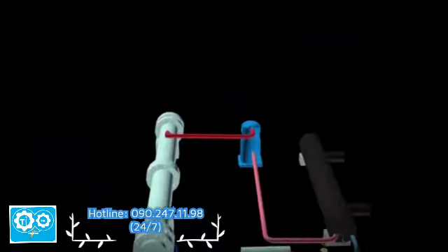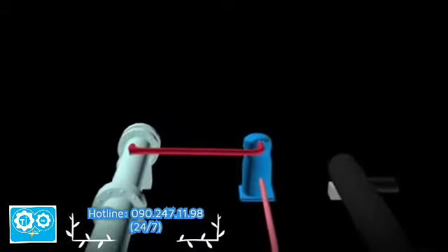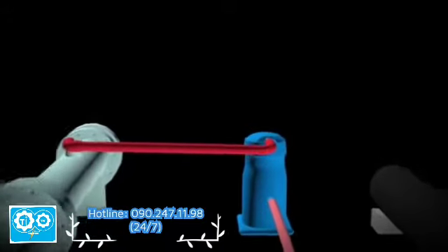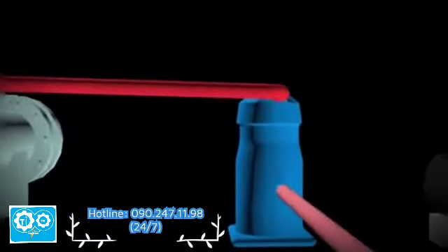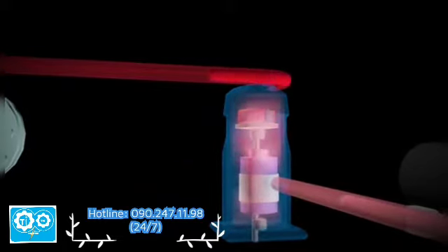Compressor. The compressor works to increase the pressure of the refrigerant. In addition, it also serves to increase the temperature of the refrigerant higher than the temperature of the condenser water so that heat transfer can occur in the condenser. The refrigerant enters the compressor as low pressure gas and goes out as high pressure gas.